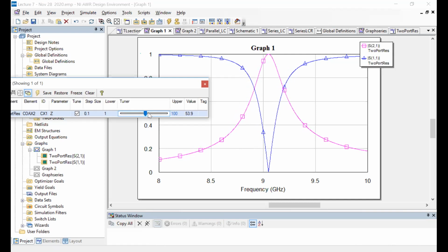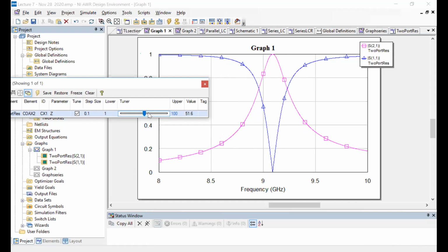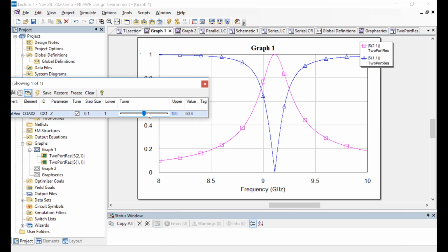Because we saw that a lambda by 2 and a lambda by 4 with the same coupling capacitor actually have a different effect on the loading. So let's see if we can work this out. If I increase the characteristic impedance, then that corresponds to a lower capacitance of the effective model, which means it will get shifted more by the presence of the coupling capacitors. So that's why this makes sense.